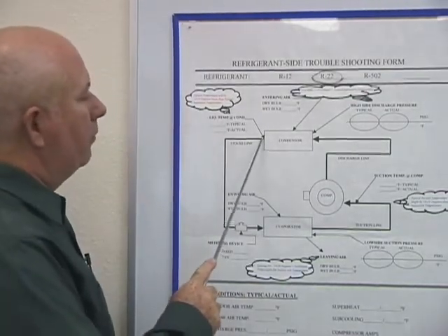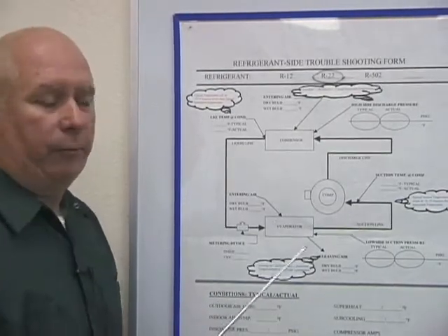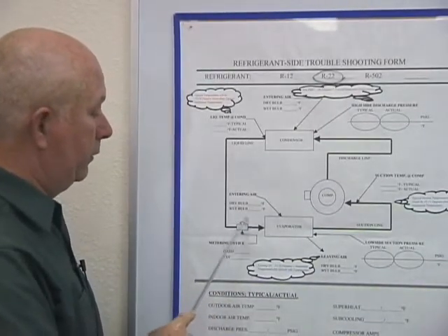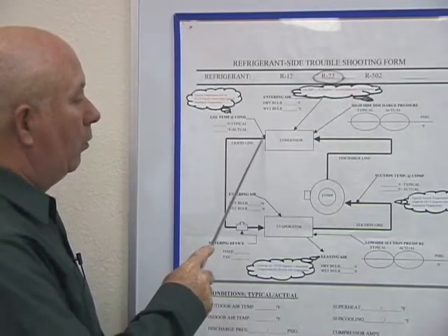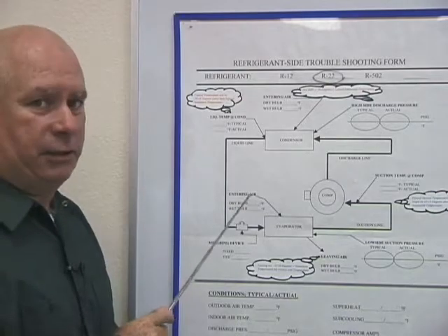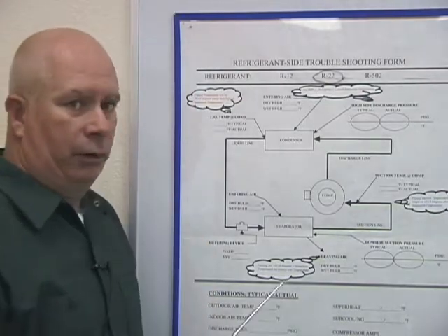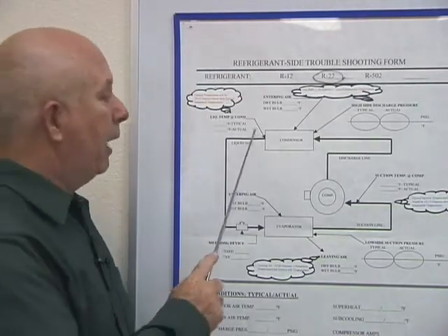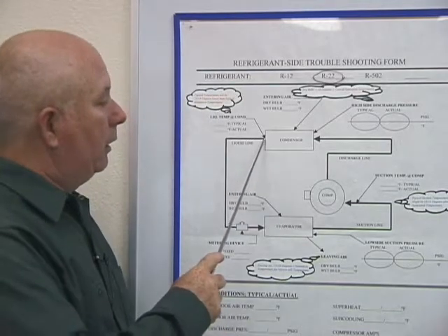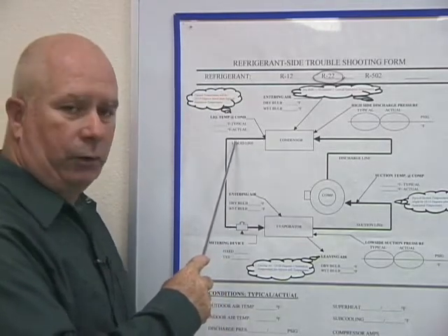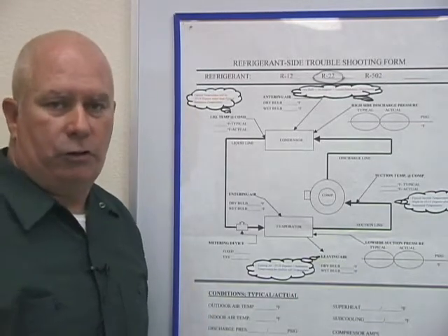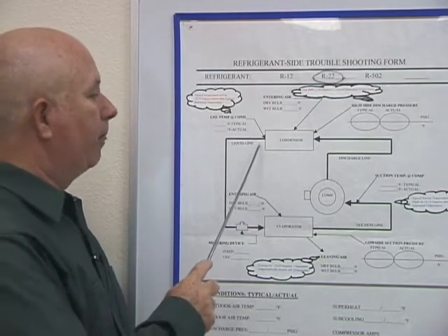So again, be a couple inches away, because now this is your liquid line, remember, going to your metering device. So what you are trying to do is get the liquid temperature. Now, of course, common sense tells us we can't drill a hole in there and get the liquid temperature. But engineers along the way have figured out that, hey, look, if the refrigerant liquid is flowing through here, your pipe temperature is going to be a certain temperature degree.